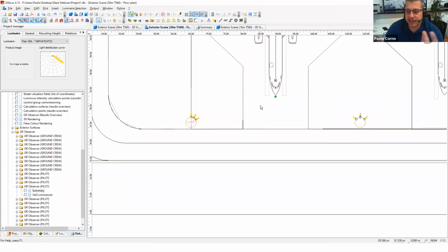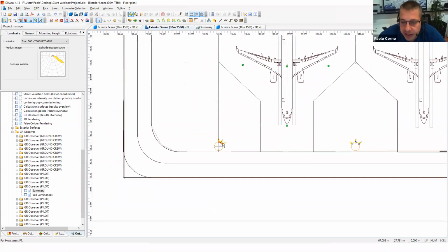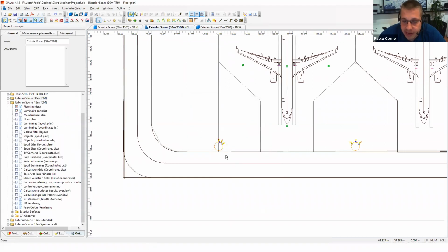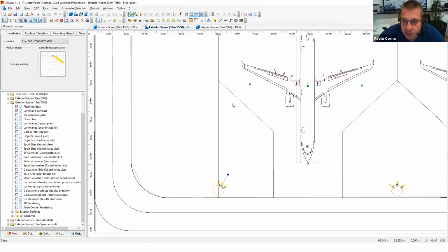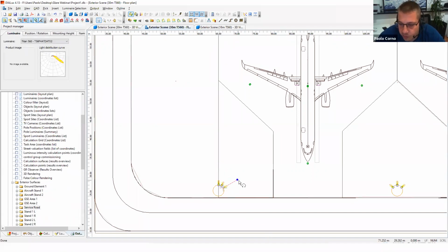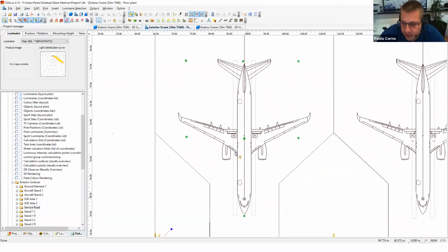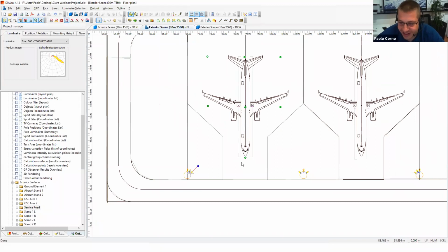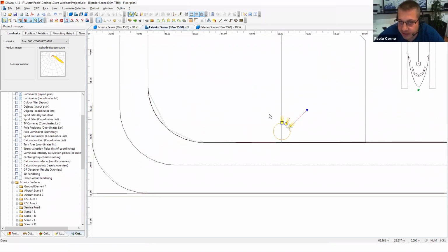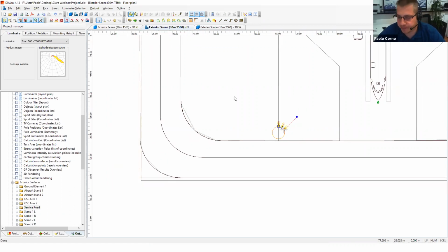So, for example, if in this case we had to live with 18 meters, we couldn't do anything, what we would try to do is split our lighting arrangement, and then with fine adjustments, try to avoid the peak intensity of our luminaires to fall within the hotspot area. For example, here we would try to rotate them away from any direction pointing towards the center line. And of course, it's going to be a lot of trial and error work, but by doing this and reducing the tilt as much as we can, we'll be able to lower this level below 50.